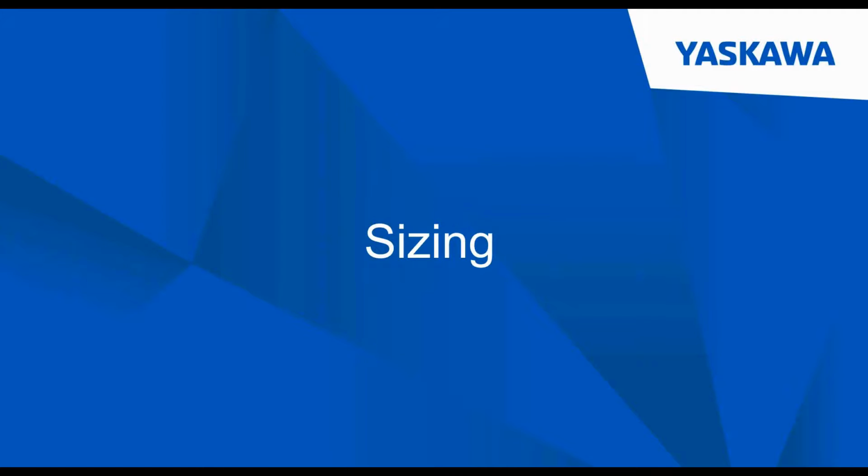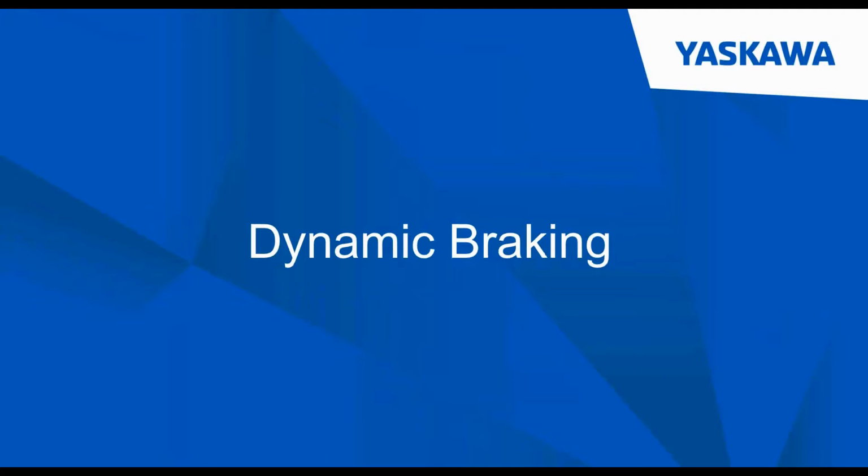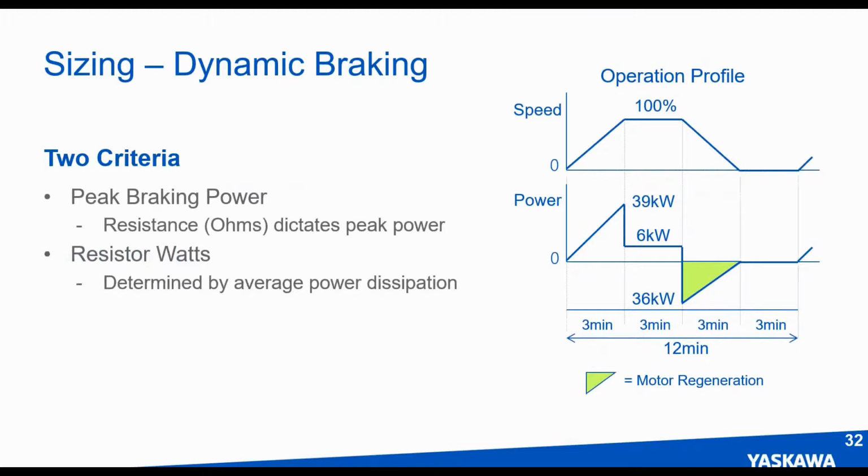So let's size each of these one at a time, starting with dynamic braking packages. There's essentially two main criteria for sizing dynamic braking: peak braking power and the wattage the resistor can handle. Resistance determines the peak braking power. The lower the resistance, the higher the peak braking power a resistor can dissipate. Wattage determines your average braking power. This is the amount of energy that the resistor must dissipate over the entire run cycle. The combination of these two is how you select your resistors.